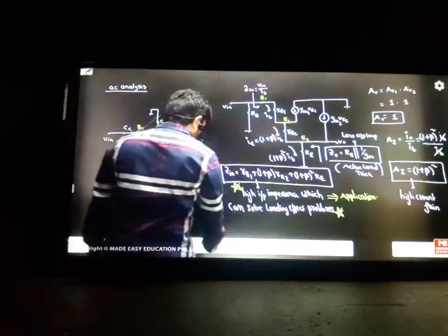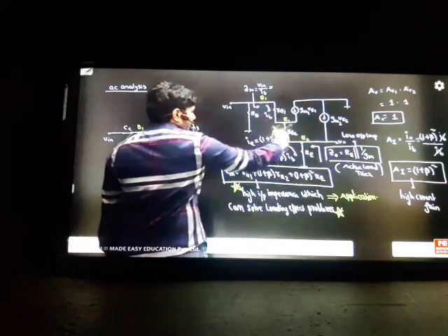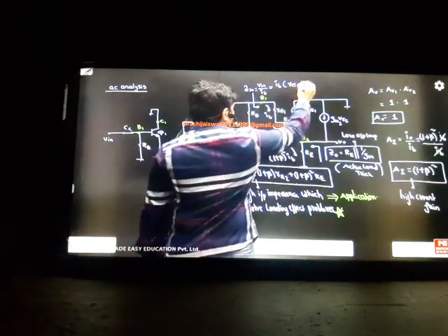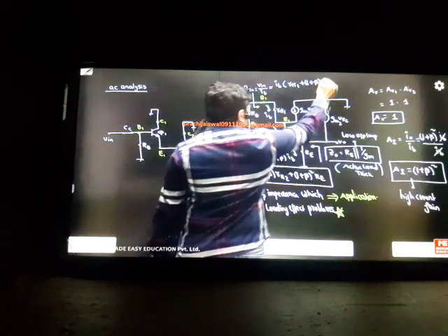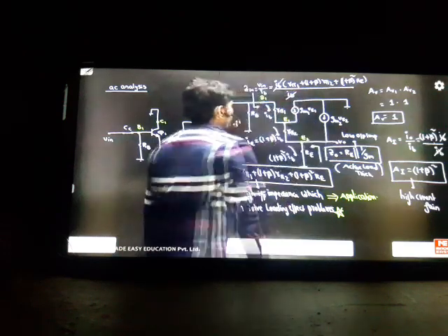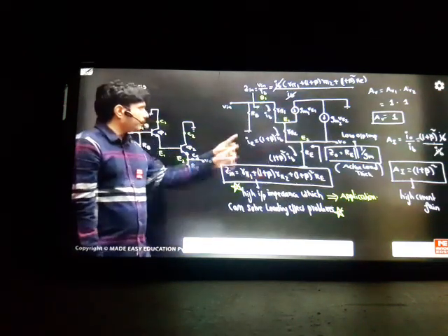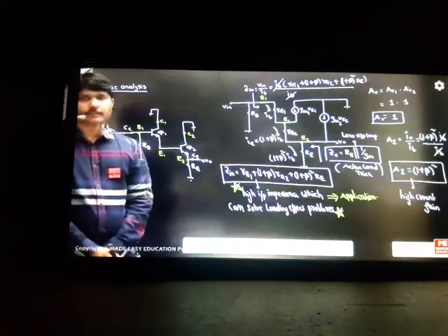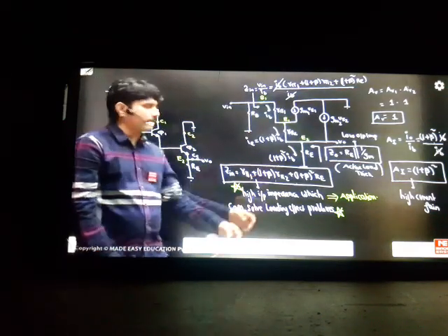If you want, I'll write it here. If you have confusion, you can have one more step here. For your input voltage, you take IB common first. This is R1, this is 1 plus beta into R2, plus 1 plus beta square times RE. This is the way I'm doing it. So IB is taken common, and at the bottom IB cancels, and this formula comes. Samresh, I think that is your doubt I'm expecting. IB will be cancelled so the remaining factor becomes your input impedance.